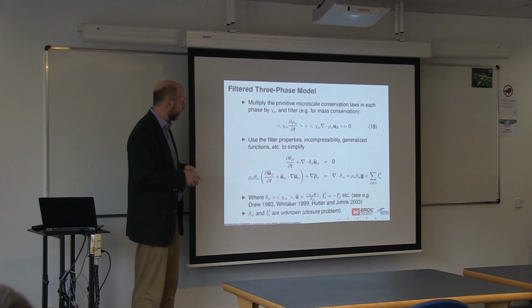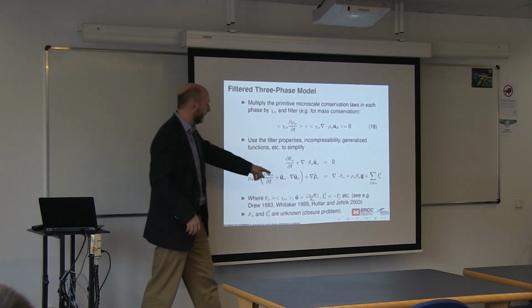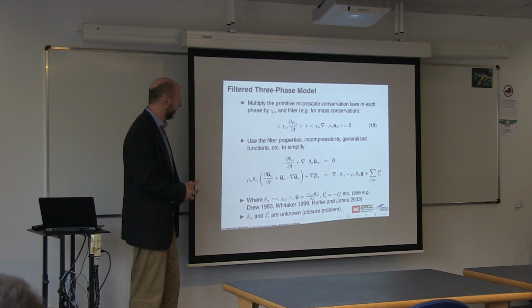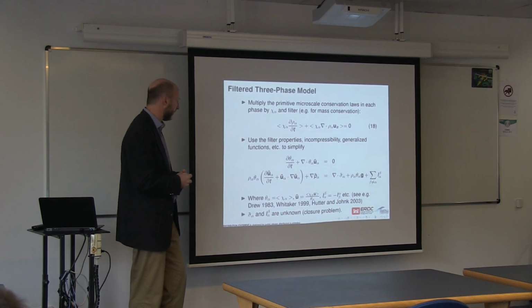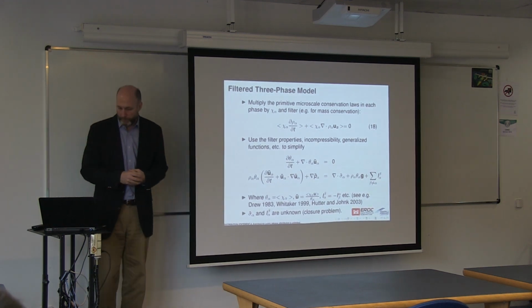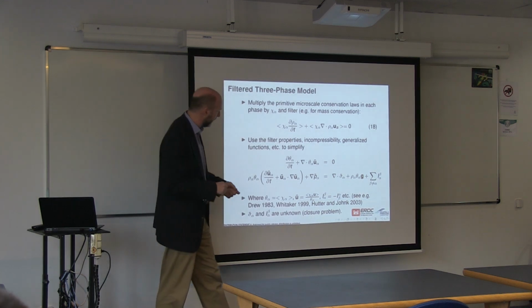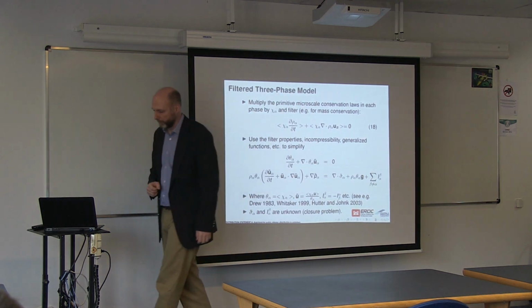If we're just thinking for simplicity about water and solid particles, then these are effectively the upscaling of the drag and the lift. So they're the averaged contributions of drag: momentum lost from the fluid phase into the solid phase, and then the matching term in the other direction. So in this slightly simplified form, I get the interface terms needing closure, and you also would need to come up with a new macroscale viscosity or stress tensor.